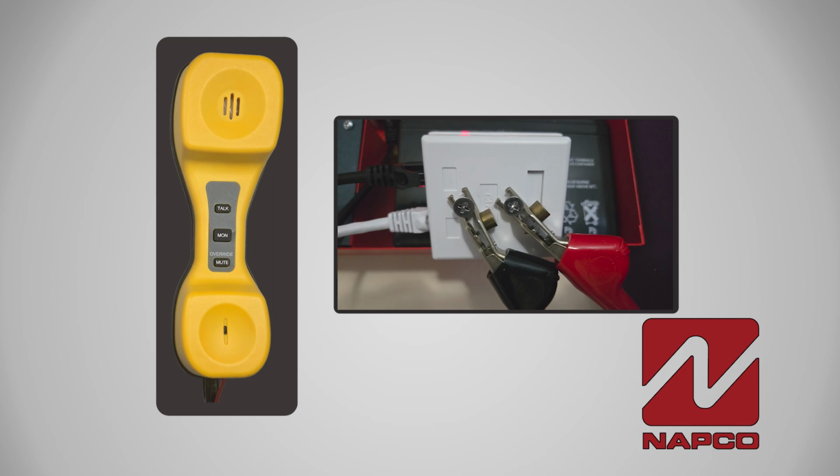If it does, this tells you the radio is capable of listening to the dial out of the alarm panel, and it is also capable of responding with a handshake. Now, put the butt set on monitor and trigger the transmission on your alarm panel. I usually recommend triggering a trouble on a fire alarm panel so you aren't clearing out the building.